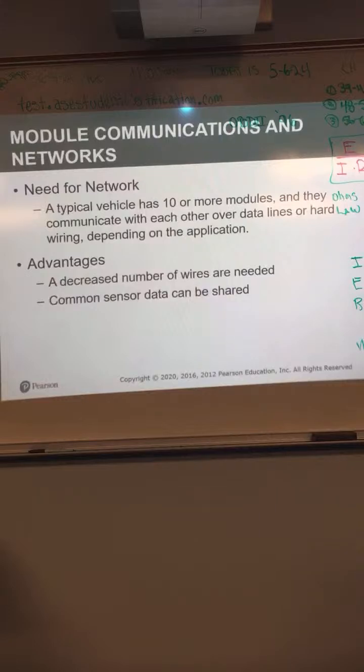Typical vehicle can have more than 10 computers on it. They have to communicate with each other. They do it through serial data lines. Advantages are decreased number of wires and common sensor data can be shared.